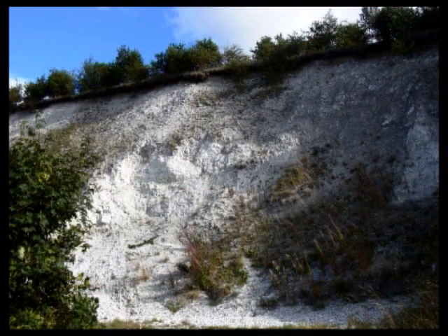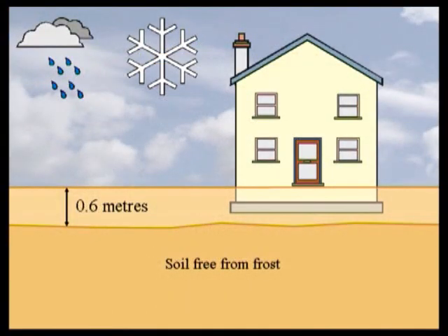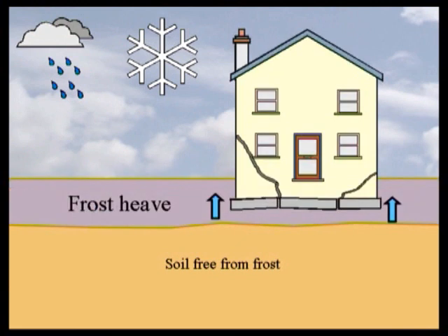Some chalks and fine sands are subject to frost heave. In wet, freezing conditions, the ground near the surface expands. In these soils, the foundation should therefore be at least 600 millimetres deep.